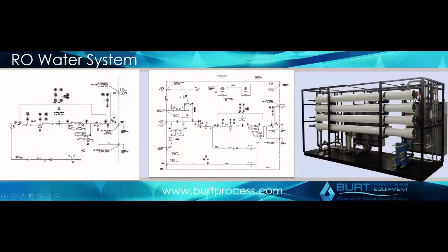This is what an RO looks like. You can see here on the right, you have your high pressure feed pump. This is where you have your pressure and reject monitoring in those cases. And this is your array of membranes. Here you have a 2 by 1 by 1. This is your feed water in. This is your end permeate out. The reject of the first set of arrays goes to the second, goes to the third. This is your final reject. And then all these combine to form your overall permeate in these cases.